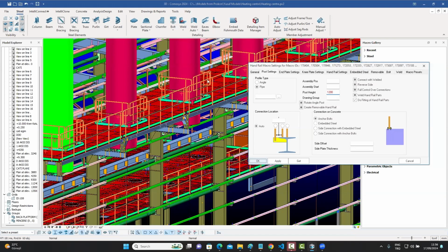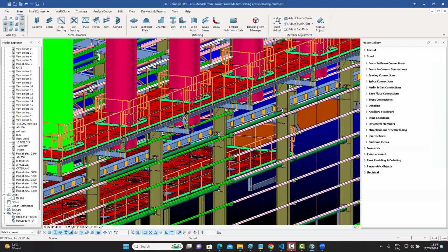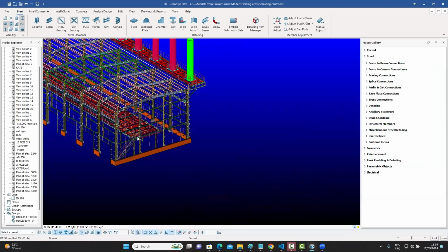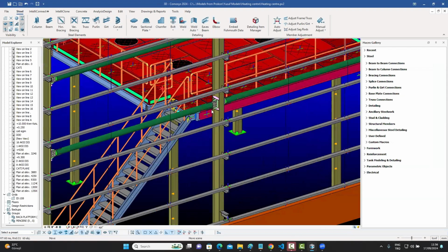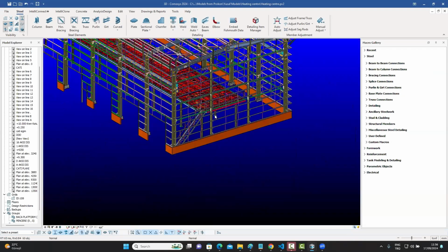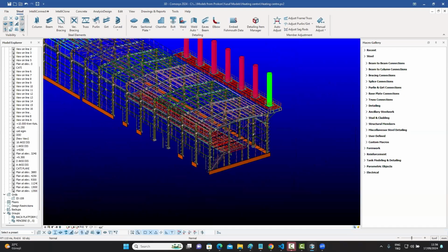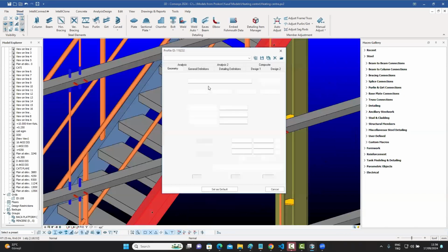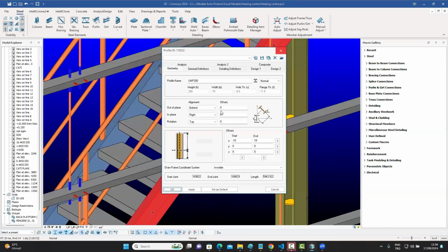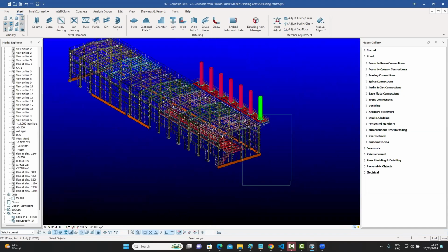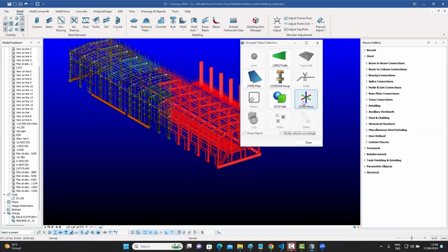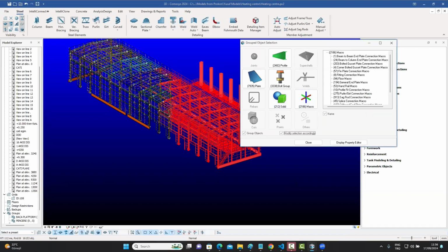And at the end of this, I will show you that I will realize that I didn't actually want to change all of them. I actually made a mistake and I wanted to change only these ones, but I've accidentally changed even the handrails which are over here, which are on the stairs. And I don't want to change that. And I don't even know how many stairs there are, but I know the stringer profile is UNP 200. So that's the information I have. And I just go once again, select the entire building, go to my macros, go to my handrail macro.